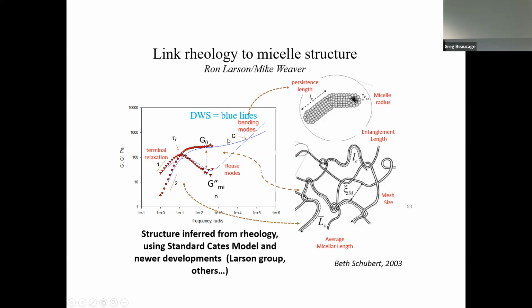If we're doing something like simulations of polymer flow, this becomes really useful, because simulation of polymer flow starts from the bottom, from here, and then goes over here to predict what you see in an extruder, right? If you can't see this part, then all this is guesswork. Then oh, it worked, you know. It doesn't always work. We don't know why, because of what happened initially at the small scale. So if you can't verify your models at this scale with some technique, then you can't really predict over here where you really want the data, right?